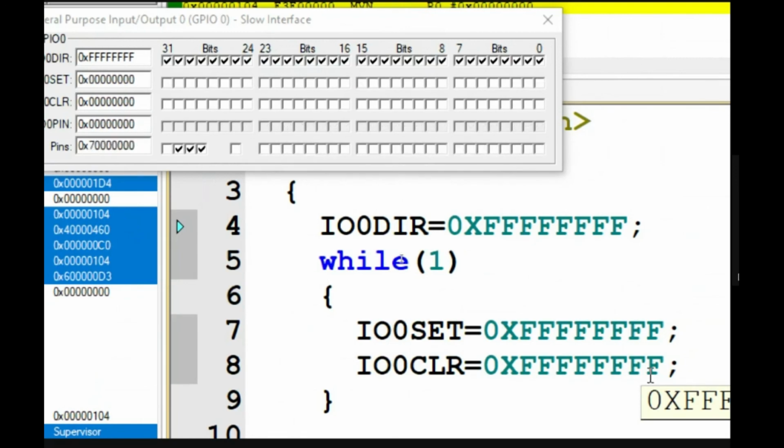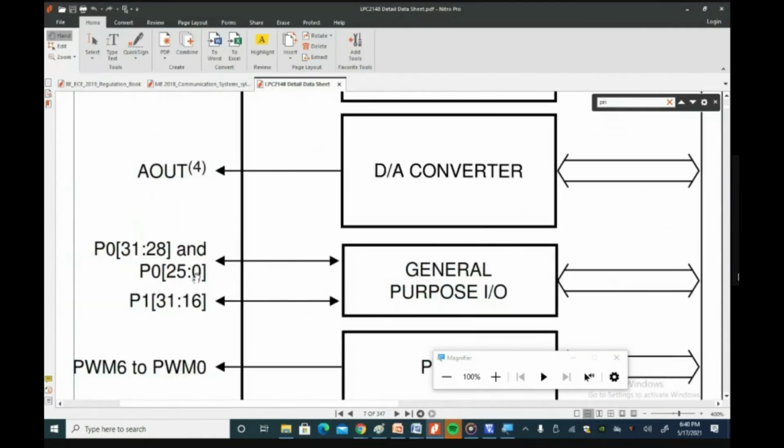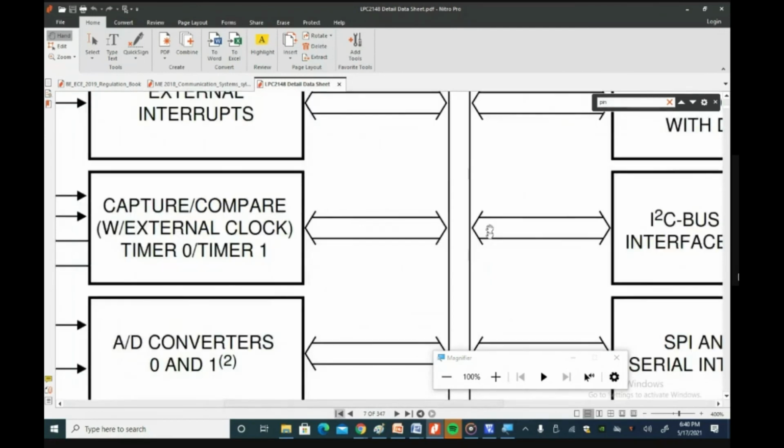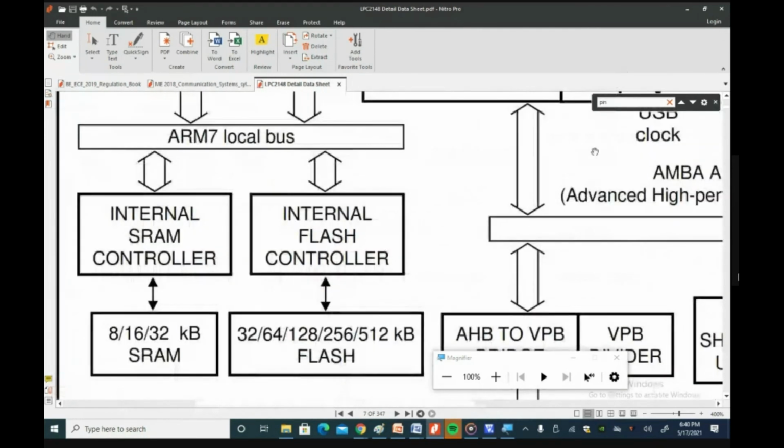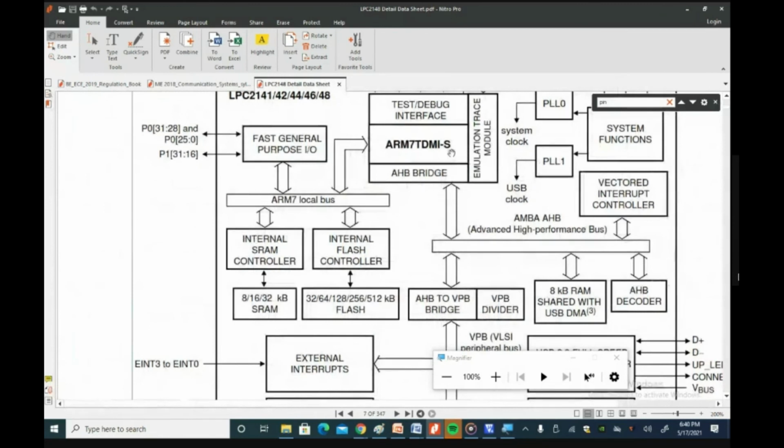It is a good way to begin with Keil, because the LED is blinking in the simulator window. What we can understand here is very important and very interesting. Now we can understand how the ARM processor inside the LPC2148 microcontroller is working, and the program that we have written is there inside the 512 KB flash memory, because the program has entered the flash memory of our microcontroller. So flash memory is being utilized properly. And because they are memory mapped registers, Port 0 are the memory mapped peripherals. So those memory mapped peripherals are in the RAM, because it is rewritable memory.